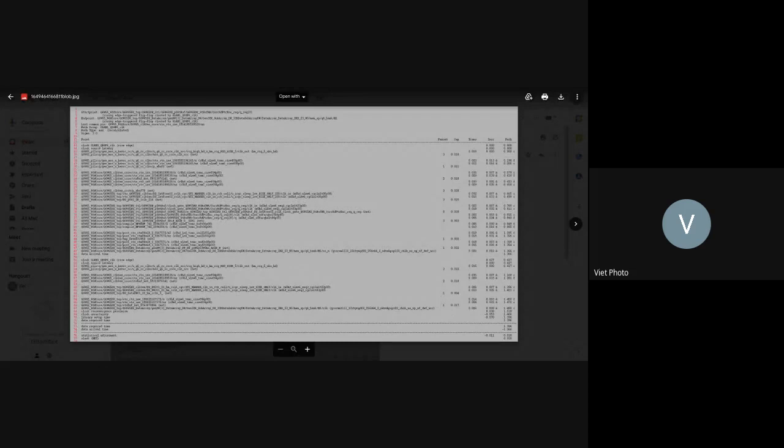So what can we do? We know that uncertainty is handled with the worst case scenario, which is if the capture happens earlier, right? Earlier is the worst. So we will take it as 900 picosecond, the arrival time for the capture clock. Because if it happened at 1.1 nanosecond, then it helps, since the clock will be later. So we have to take the worst case scenario. That's why they add it.